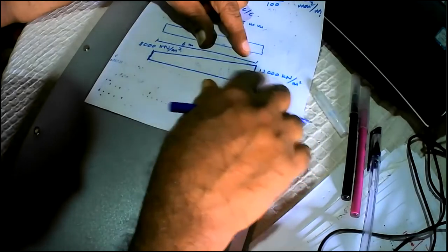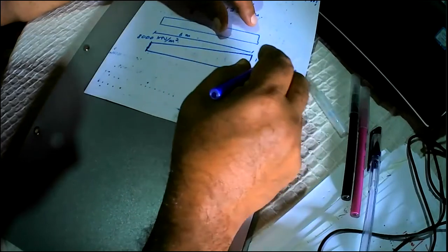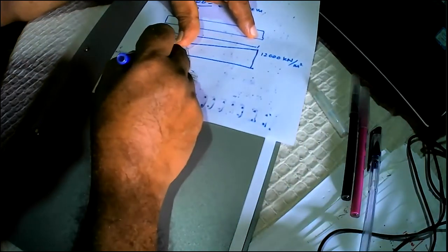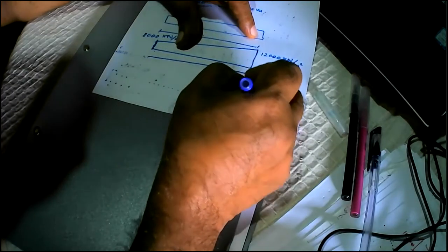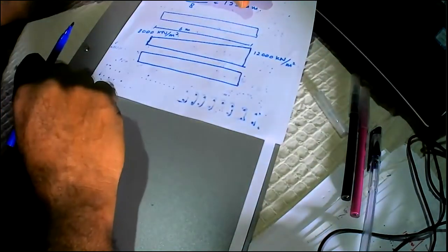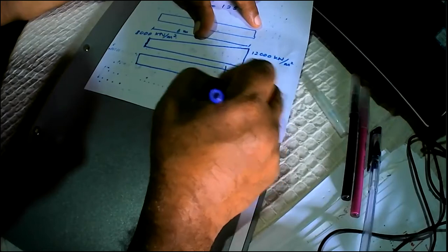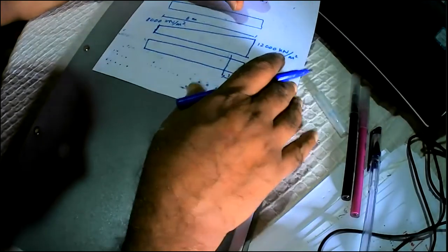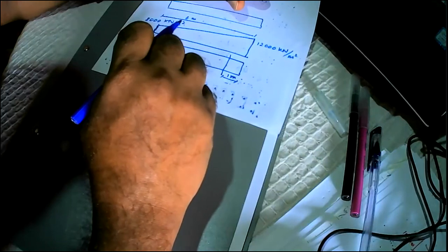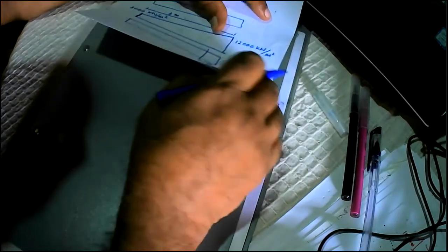So you can see if we get something like 12,000, then there's another way of finding the reinforcement. And this is applicable if the whole wall is in compression. Whole wall is in compression, like this case. Throughout the wall, it's in compression. So what we do is we consider 1 meter length here, and consider that the stress is 12,000 kilonewtons per meter squared. And then what you are going to do is